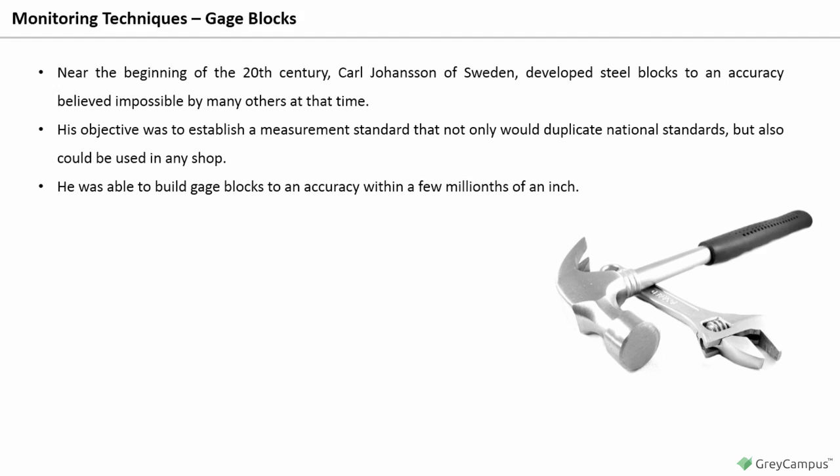They are used to set a length dimension for a transfer measurement and for calibration of a number of other tools. We generally distinguish three basic gauge block forms: rectangular, square, and round. The rectangular and square varieties are in much wider use. Generally, gauge blocks are made from high-carbon or chromium alloyed steel. Tungsten carbide, chromium carbide, and fused quartz are also used. All gauge blocks are manufactured with tight tolerances on flatness, parallelism, and surface smoothness.